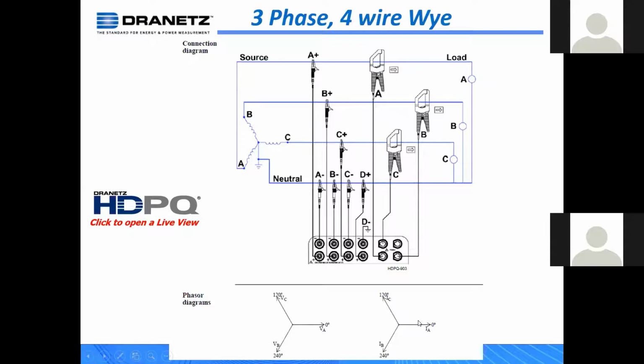I'm going to leave my cursor here. Rotate that vector counterclockwise. And I'm sorry, the cursor disappeared. So you could see A would come through that first, then B, and then C. It's a counterclockwise rotation. So that's how you would compare when you see A voltage and A current, you could see their relationship and see if you're wired correctly.